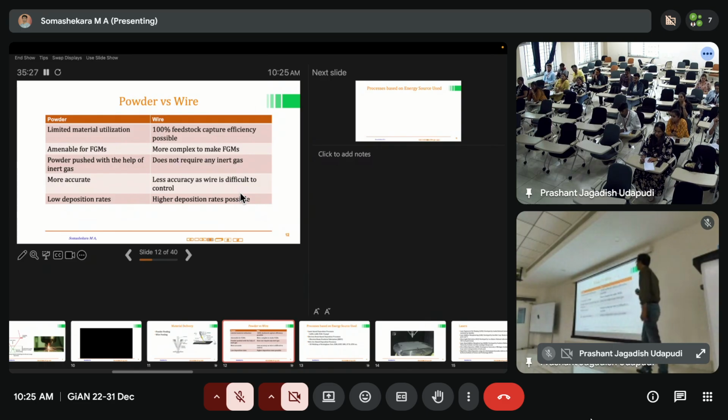If you don't properly maintain the gas feeding. And when it comes to printing some composite structures or FGM parts, you may have better flexibility with powder, because there you can mix different compositions of powder. With wire you can also achieve it, but it needs a little more planning and is a little more complex, because you need two different wires feeding together into the same pool, where you may find different alloy formation, etc. But if you can manage your compositions, you will get it here also.